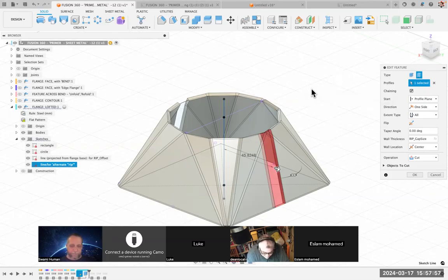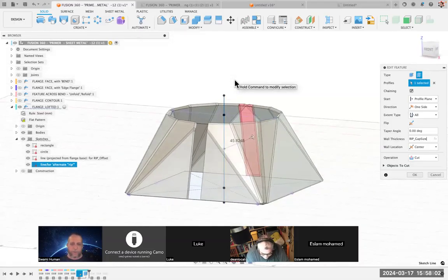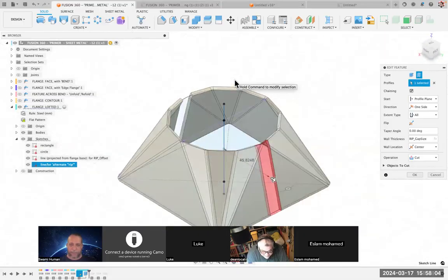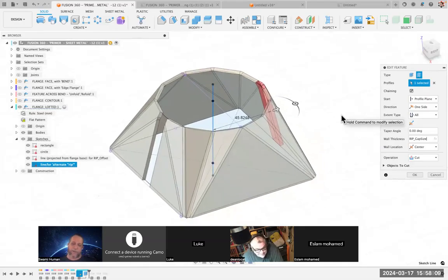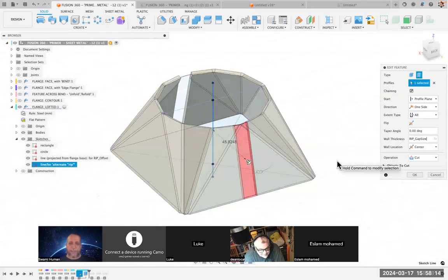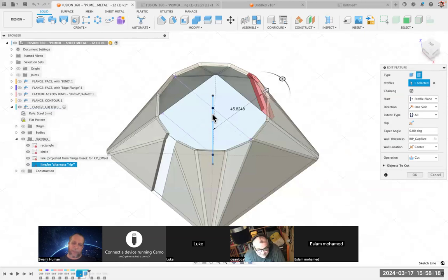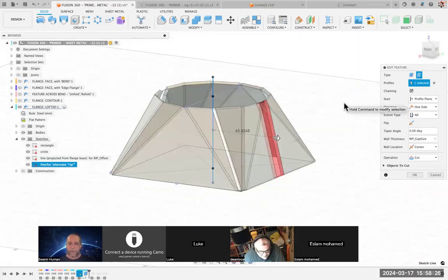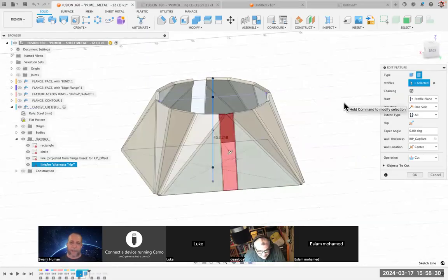And they have a rip feature, but it has the downside that we noted. It's going to move around in certain cases when you change the geometry, like if you're prototyping or something and you're not exactly sure what the final geometry is going to look like. So in order to deal with that, depending on how things change, you might be able to get away with it better by making a line, then extruding it through, and then you're going to get the split that you need to make your flat pattern.